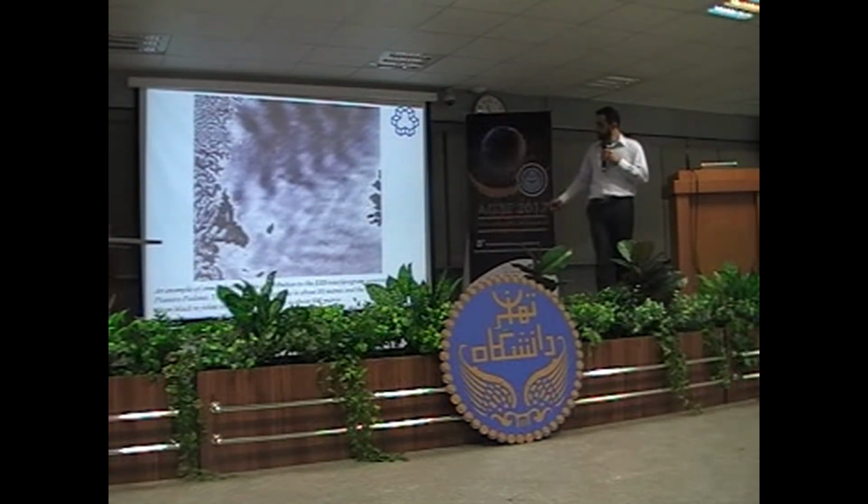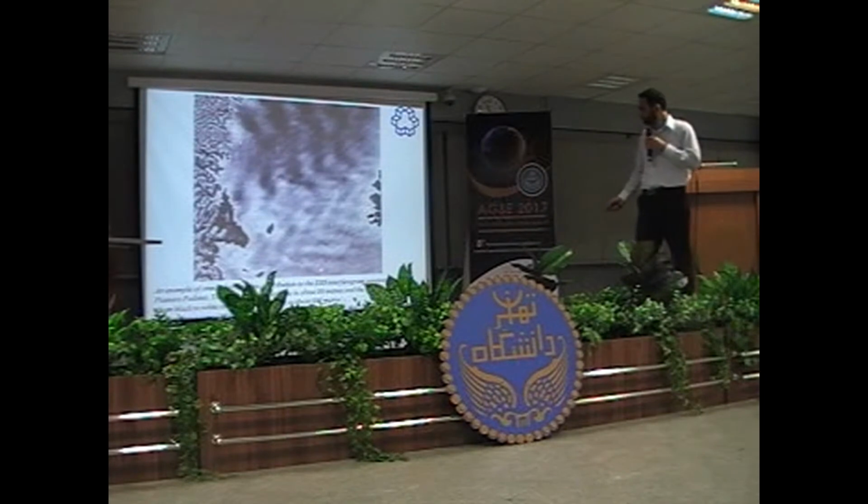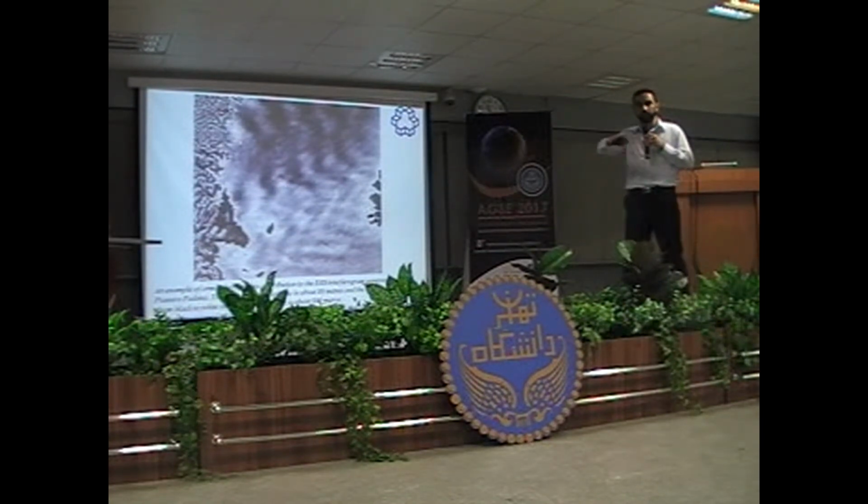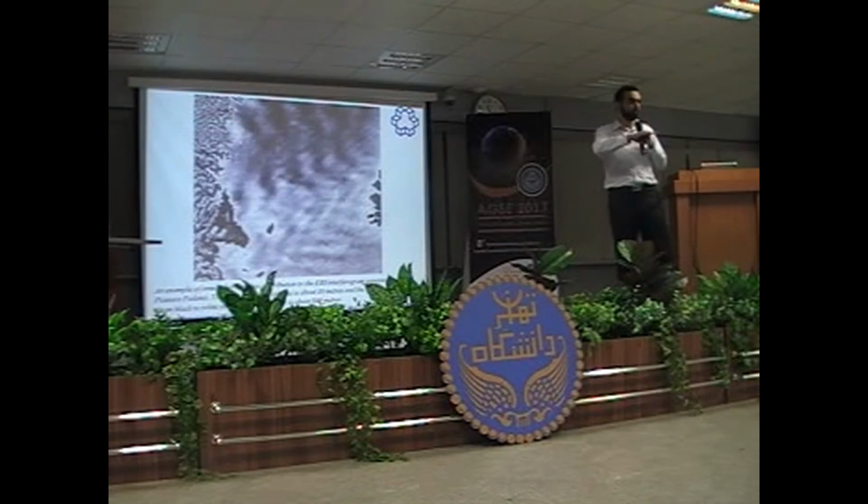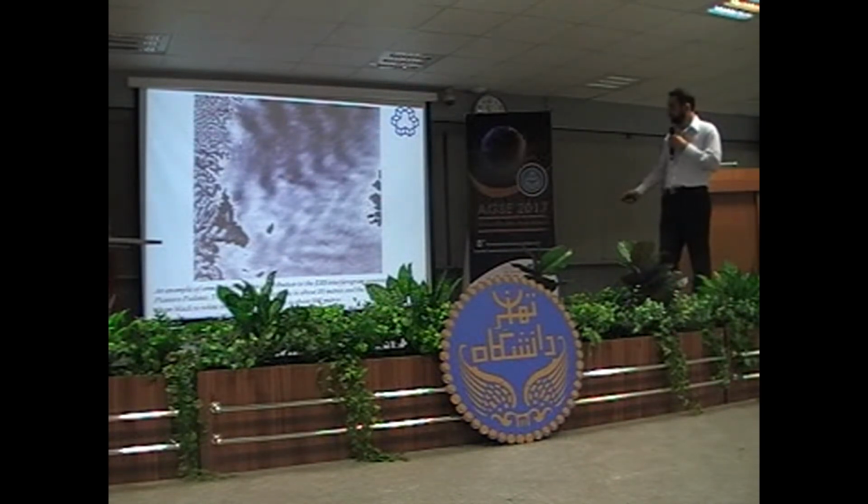This is an interferogram, and this is the flat area. After removing flat earth, we're expecting this part to be completely flat. No pattern, no fringes. But you see, there are some effects, and these effects are because of the atmosphere. The two acquisitions are in different atmospheric conditions.